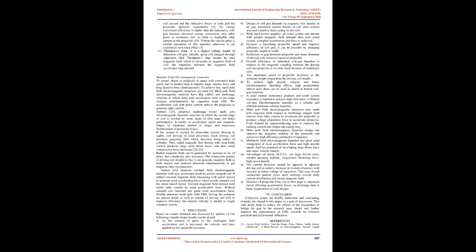Induction coil gun launchers have high conversion efficiency. When the coils are fired, eddy current is induced in the projectile, which produces a repulsive accelerating force. To produce a greater force at the beginning, a pancake coil is added at the bottom of the coil. It accelerates a heavy projectile to a much higher velocity.